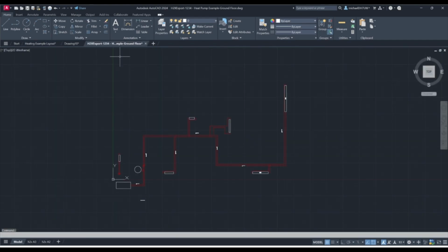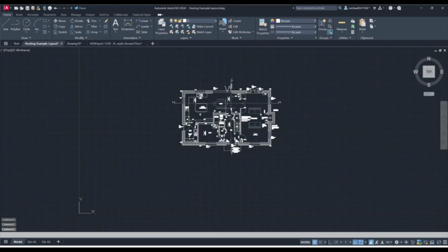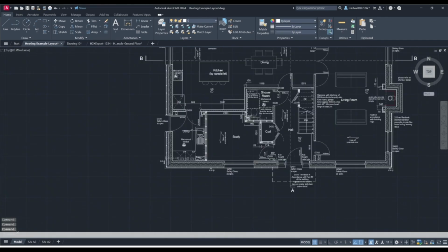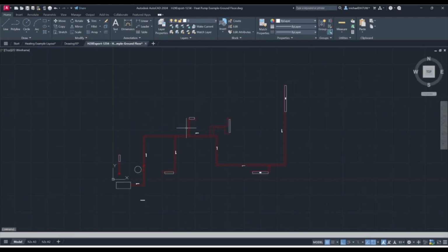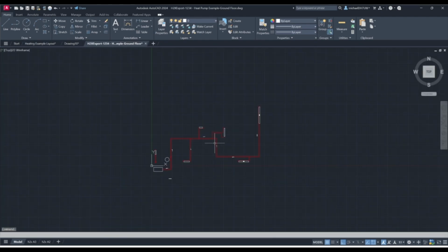I would recommend taking more of a look into how to use XREFs in AutoCAD, because it can be a little bit of a larger subject area, and I wouldn't want to make this video too long. But yeah, you could go about that way of doing it and use reference point 0, 0 and reflect that on the drawing you are XREFing to, as to where the reference point is in h2x, which is the front left hand corner of this building. There is a simpler method though, if you just wanted to use the system design and not have the ability to detach or update the XREF.